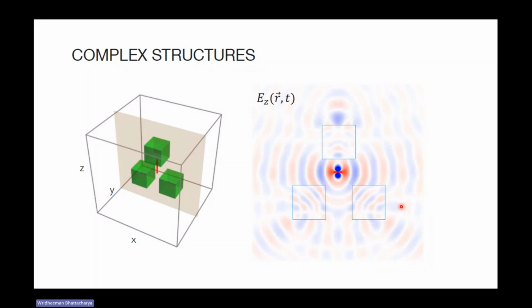So this is basically the study of how, if these things get closer, we have to increase the denominator by more, such as if lambda by 20 is there, we have to do lambda by 40 and see how the saturation point we are getting. And after that, we can say that this system is now converged and we can move further.